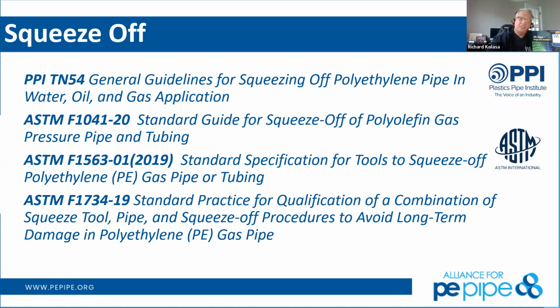So they're going, well, can I just cut out the failure, or do I have these bubbles all the way down the length of the pipe? My recommendation in this particular case, because it was only 3-inch diameter and it was DR7, so it's fairly thick walled, is they actually ended up pulling up 3 miles of pipe. Unfortunately, because we can't guarantee, because you can't send a camera down that small diameter to see if you have any deformation of the wall and interior of the wall.